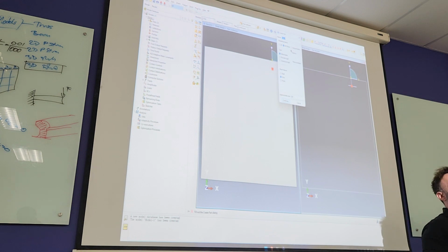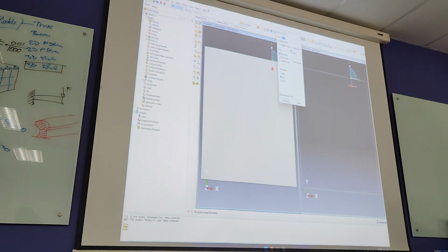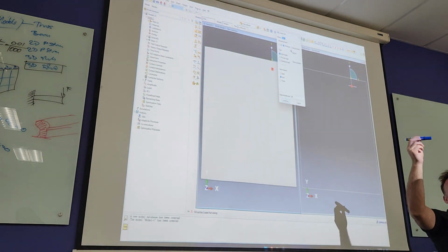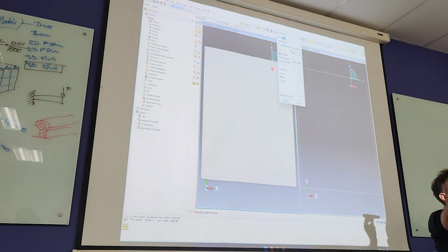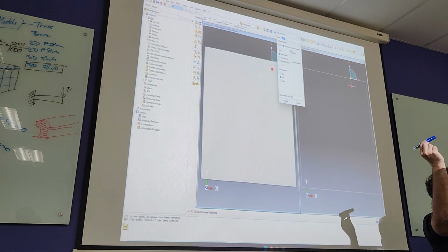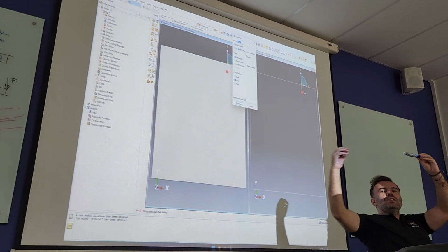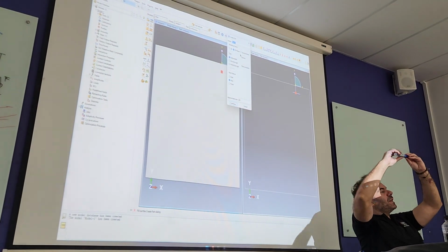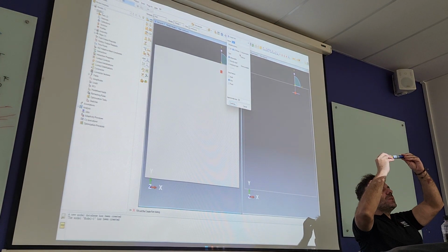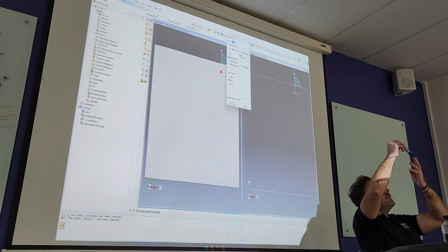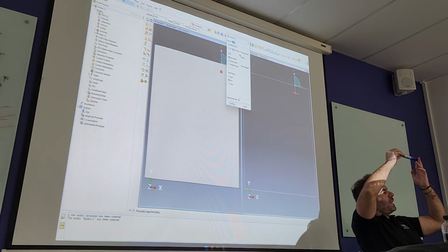3D, obviously, like, we can have 3D beams, we can have 3D space, but it's important to understand that a truss, like a spring, is a one-dimensional object. It means it can only change or deform in one dimension. But that one-dimensional object can live in 2D or 3D space.